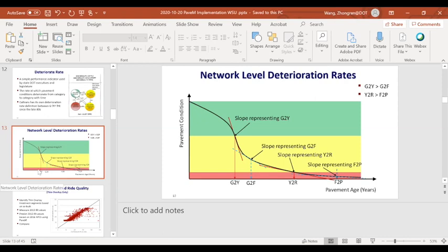We define it as, say, alligator for AC pavement, your alligator cracking has to exceed about 30%. We only count this wheel track alligator cracking, and measured by length. So that's very detailed. But for the red pavement, AC alligator cracking has to exceed 30% before you call it red, and you have individual definitions for all these types of things, right?